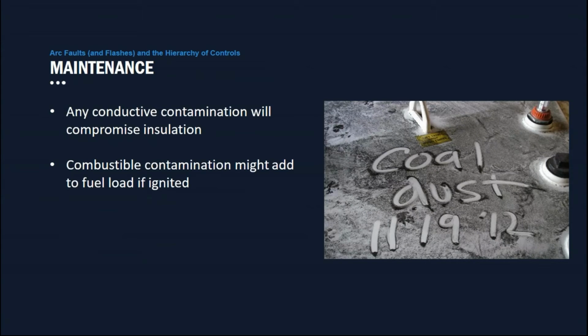Maintenance. That's a lovely picky I found. Coal dust. It tends to cover everything near a coal mine. Of course, there are other applications where surfaces get contaminated as well. Salt air is a classic, where the moist salt can also be conductive. And when we have this compromise of the insulating surfaces, then all of our original calculations have gone out the window.